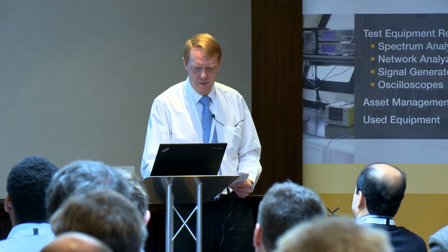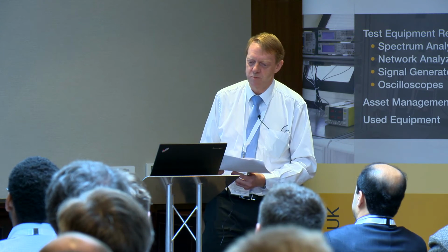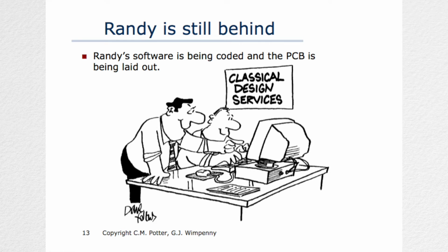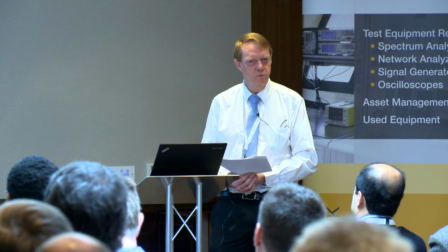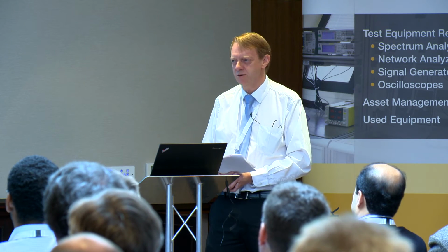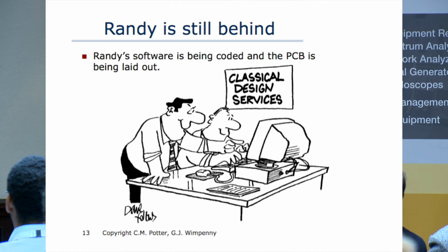So Randy is still behind. His software is being coded and the PCB is being laid out. He seems to be forever working with a PCB guy to ensure that the critical parts of the layout are as they should be, messing about with different floor planning arrangements and critical tracks, maybe adding some shielding and screening areas, and making sure that there's good electrical isolation between the bits that need it. Power planes, ground planes, all that sort of stuff is being discussed between these two intelligent-looking guys.